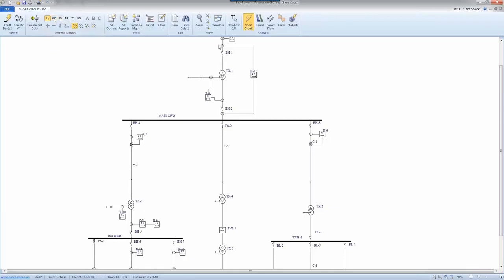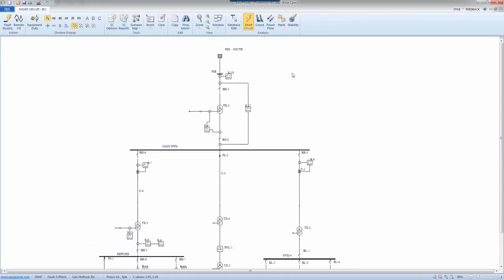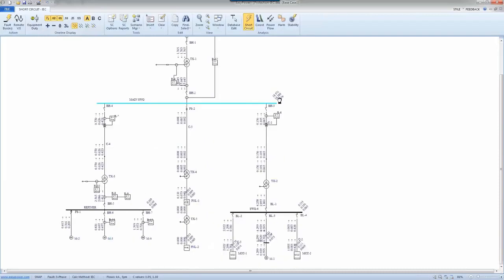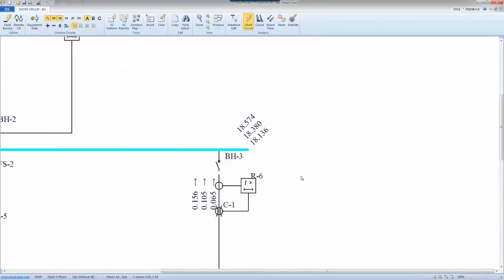So logically, you would imagine, and let's just run a fault here. If I run a three-phase fault and start showing the values, let's say breaking at 20 millisecond, breaking at 50 millisecond, as you see, the current starts decaying. And it would make sense. That's the initial value, and the breaking currents, you would expect them to drop.